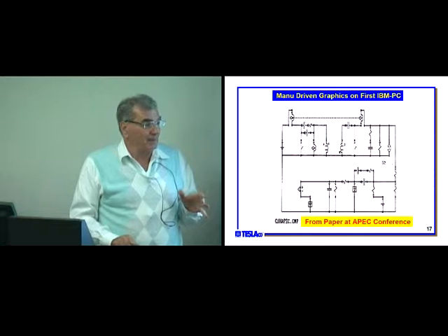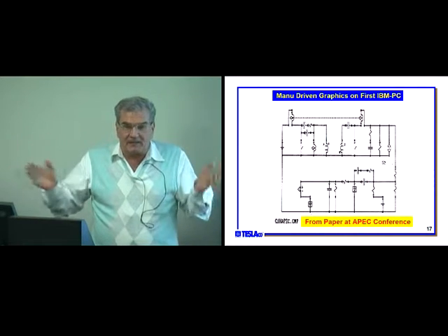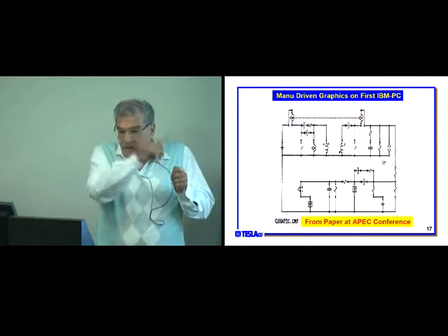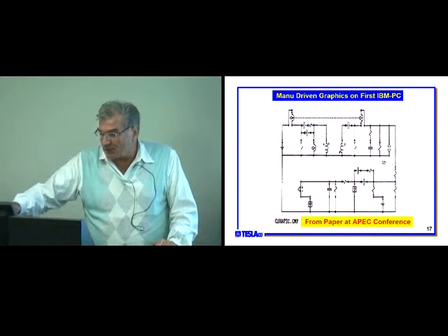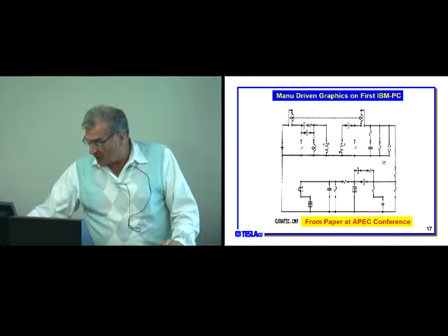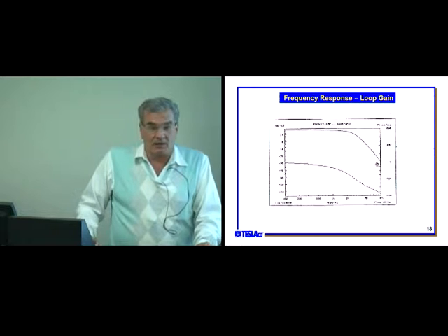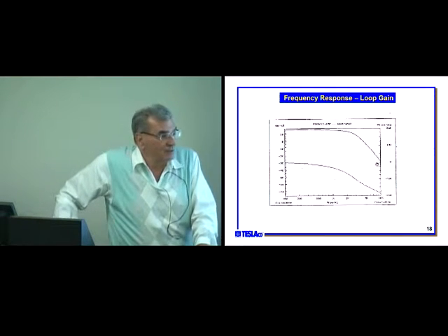graphics-driven program. Even ECAD programs at the time, you had to give a nodal description. Here, we draw the circuit with the components, and here it comes out. At the end comes out the loop gain or frequency response over the whole circuit, okay?